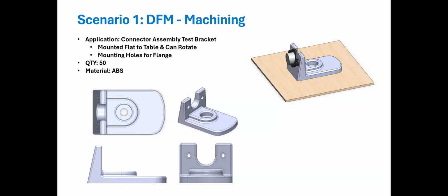That is one huge consideration. There are a lot of radiuses on this part, which will complicate the overall machining, and honestly, they're unnecessary. So that's one thing. What is another? How about reducing all the fillets, eliminating? Correct. Piggybacking off that, we could eliminate the majority of the fillets because, one, the majority are unnecessary, and two, they just add to overall costs.